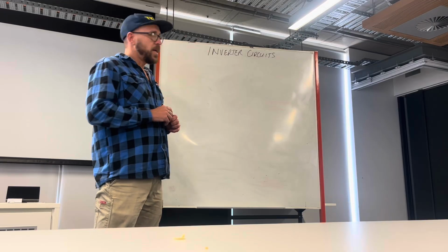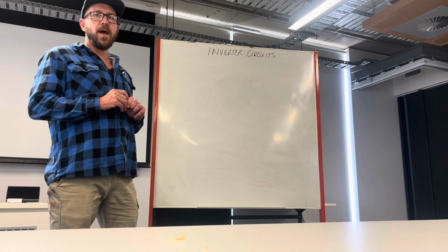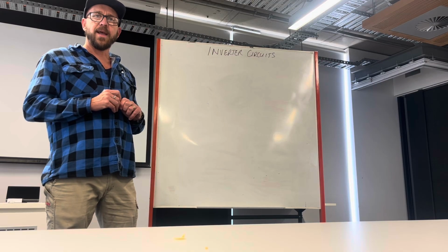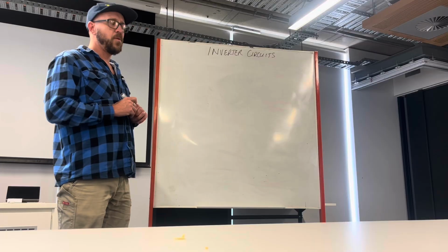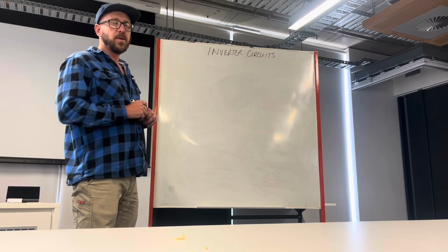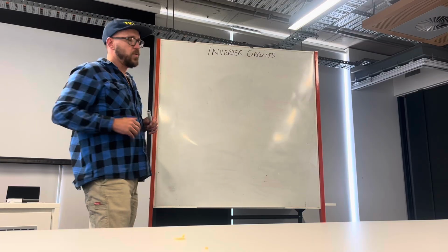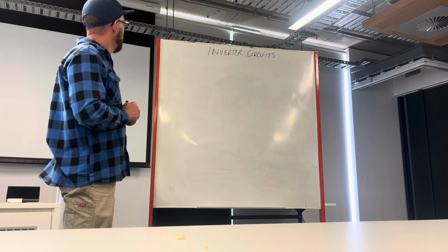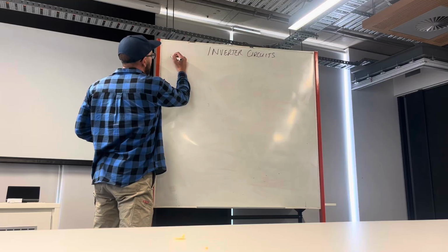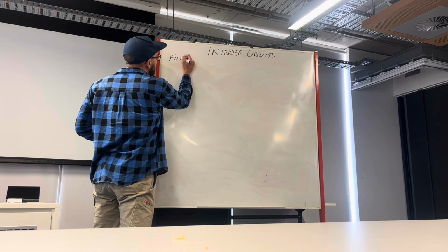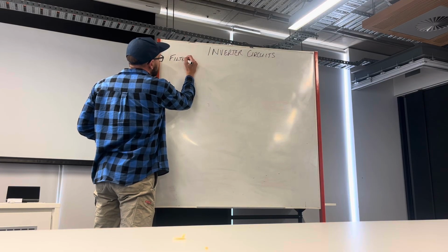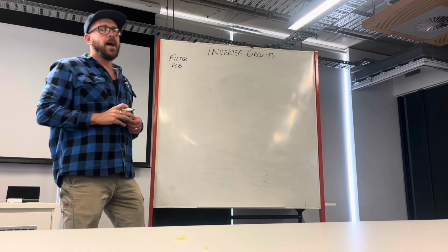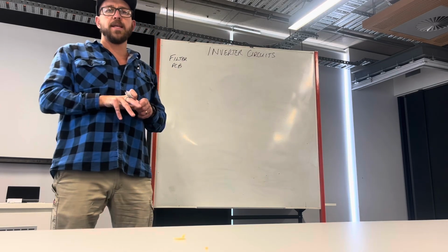So I'm just going to run through how the system works. Usually the first thing we come to is our filter components, power or filter board they might be called. So I'm going to draw it as though it's some separate boards, but remember, small system you may only have the one board. So we're going to start off, we'll have a filter PCB. We've got our incoming power into the outdoor unit.